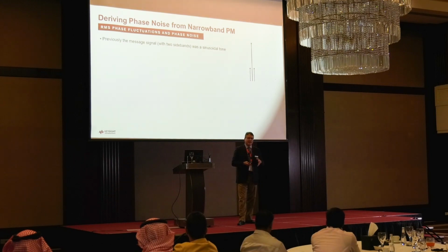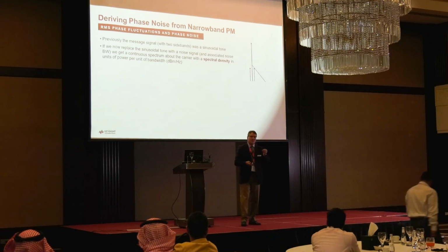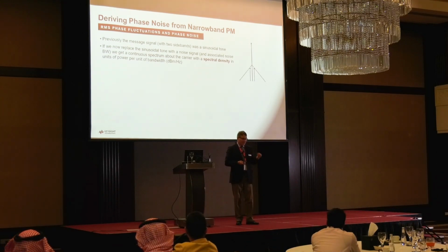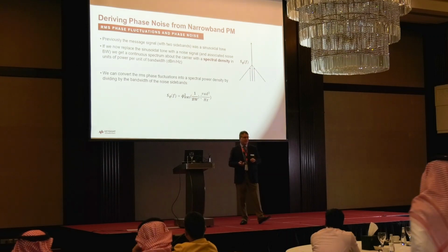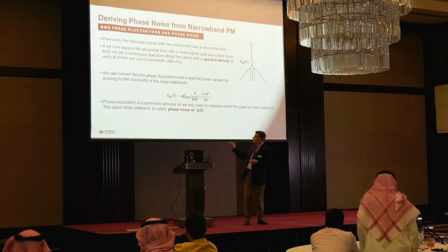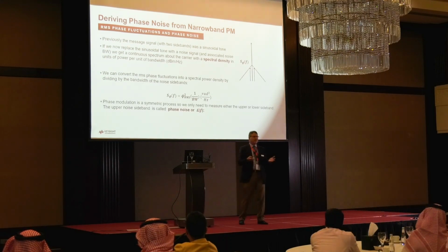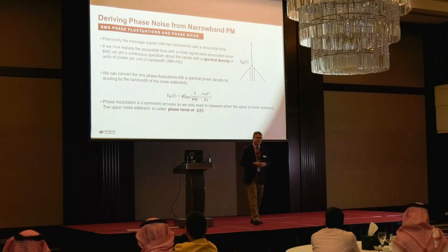So now let's take this case of single sideband or sideband modulation for an FM signal and apply that to a noise situation. So remember I mentioned for a noise-like signal you have an infinite number of sidebands. So we're measuring spectral density, energy normalized to 1 hertz. And so in this case, when we measure the actual spectral density of the phase noise power, we are going to end up measuring all of those sidebands, an infinite number of sidebands that are roughly shaped like that, the skirts of the energy relative to my main carrier.